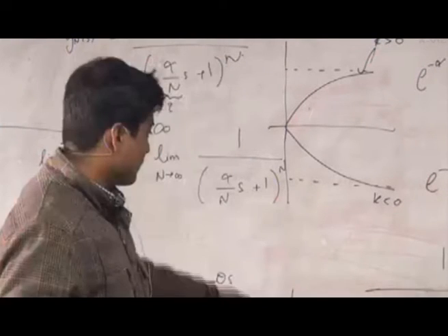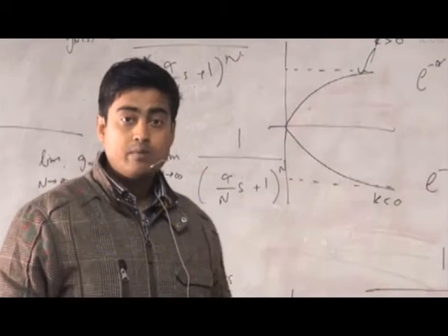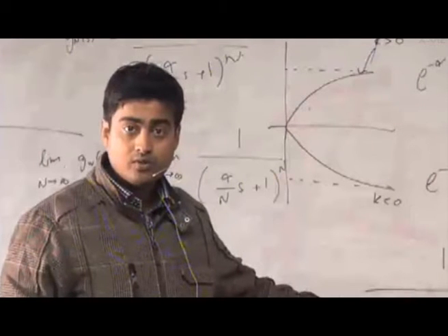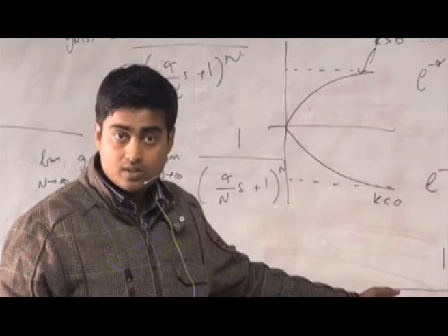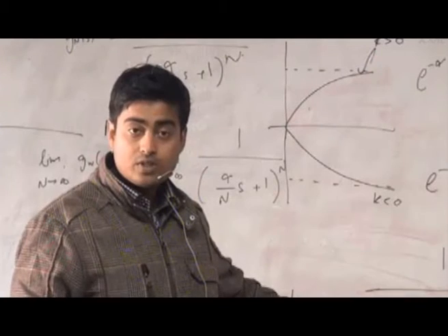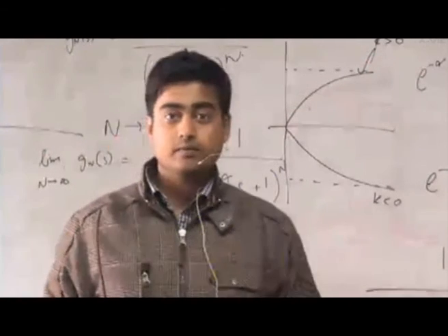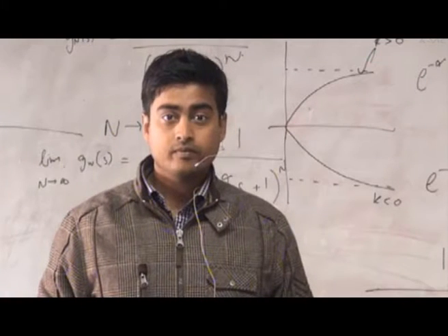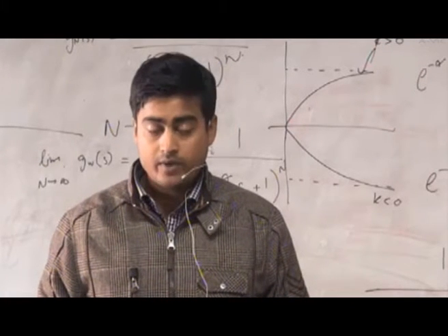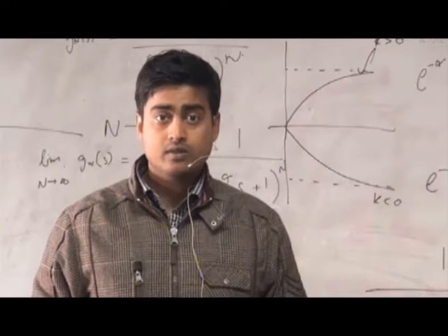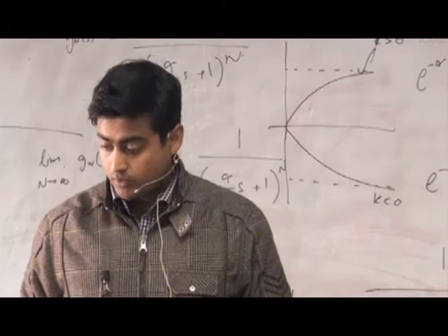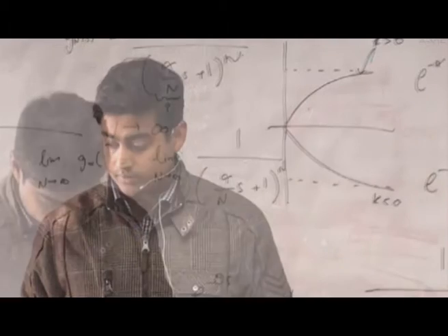Like the case we have here, if you consider a time delay system, it is an infinite order system. I cannot design a controller for this. I need to approximate it to a first order or second order system, so that it gives me ease to design a control system. This is why we generally restrict ourselves to first order or second order systems.